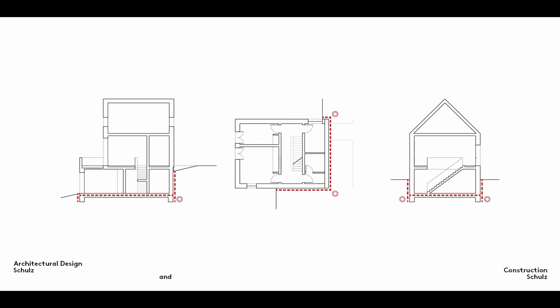This water must also be carried away from the building by means of drainage. Secondly, a building can lose internal heat through its foundations as well as its external walls. If rooms adjacent to the ground are to be heated, they must therefore also be protected from the outside against transmission heat loss by means of thermal insulation.